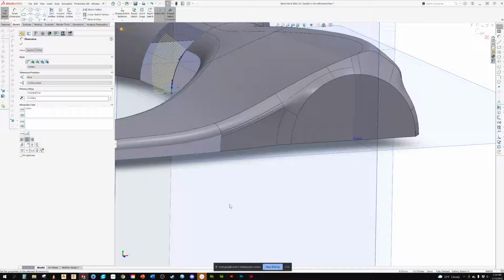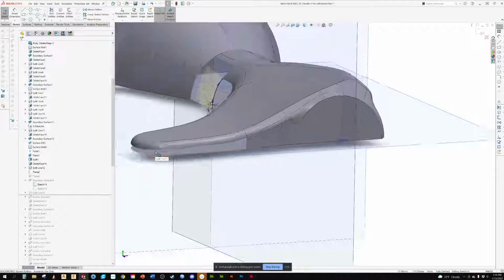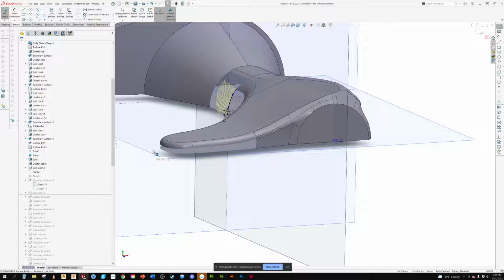You know, as designers, where this becomes important is, if it's a looks-like model, but it's not going to production or anything like that, you can get away with not putting draft in. Unless it's one of those things where draft is extremely important because it affects the visual a lot.